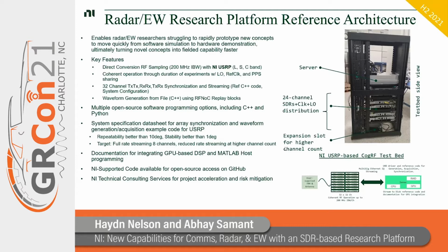In addition to the hardware elements, we have also focused on the software components. So yes, we have the benchmark rate example in the UHD driver, which is a good starting point, but we have taken it to the next step, where we have optimized the benchmark rate example by adding things such as streaming engines, by looking for the optimal way to write those programs so that you can get high data rate streaming from these large number of channels into a powerful server.